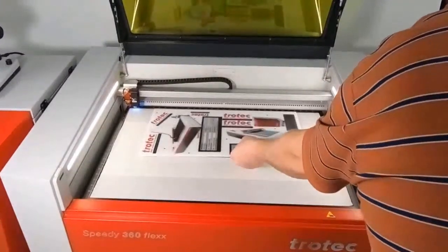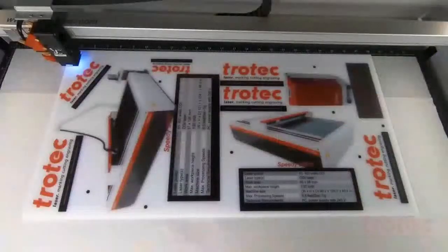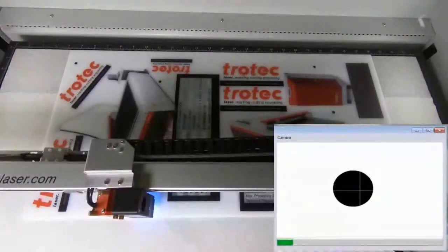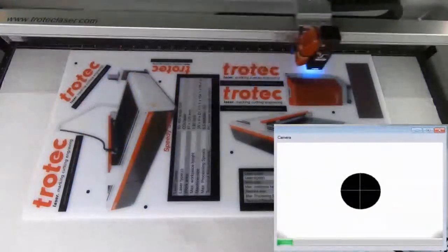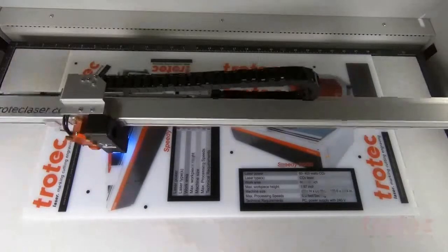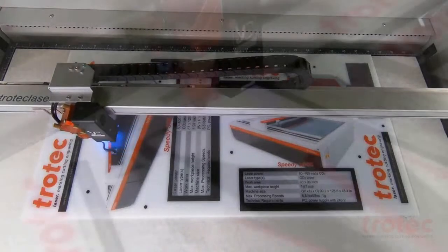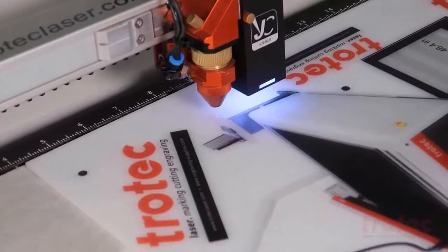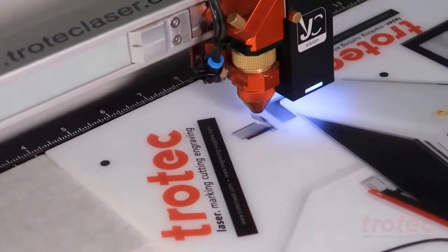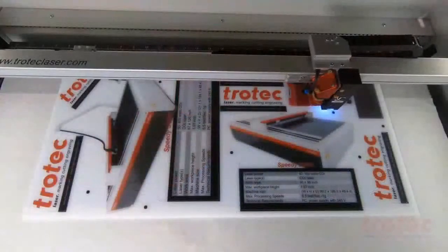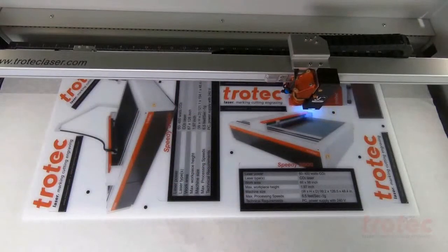The print file needs to match the cut file, so you want to break it apart into different layers or into different colors. And then the laser system is going to go out and actively search for the registration points, as you see here. And then it's going to size, scale, skew, and rotate the design so that it gives me a perfect orientation cut. So I don't have to worry about any bleed within the graphic. I'm able to get down to all the intricate little details and cut all these components out.